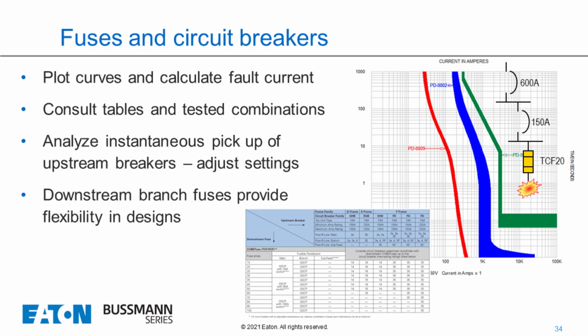As you can see, we plotted our curve. For a fuse breaker scenario, we definitely have to plot our curves. And then we also have to calculate the available fault current to find out where it falls into play.